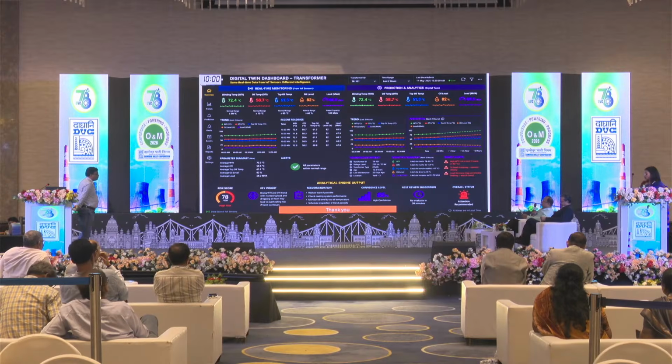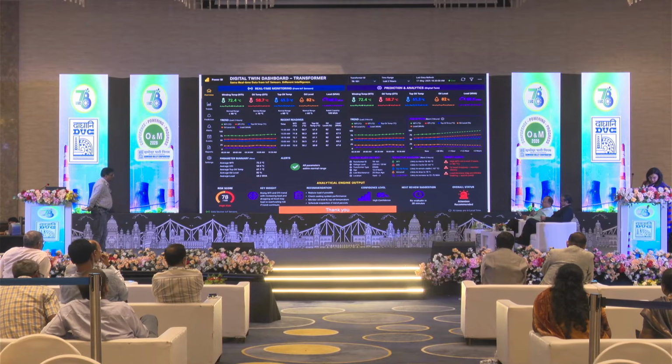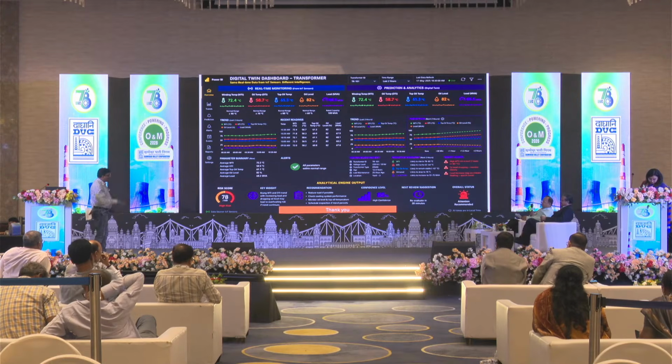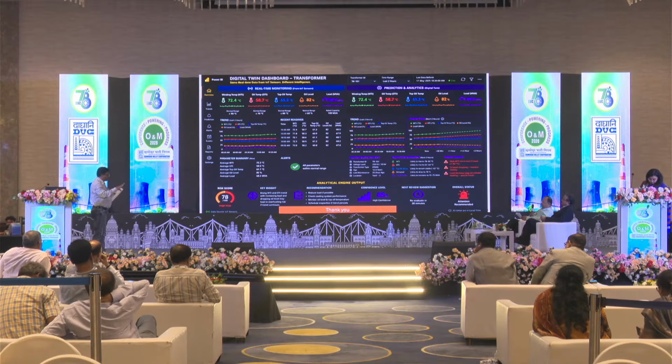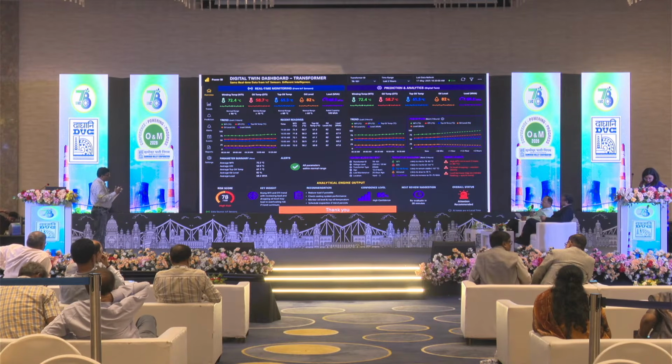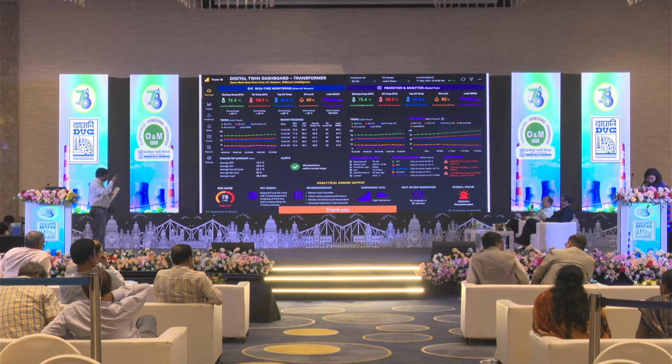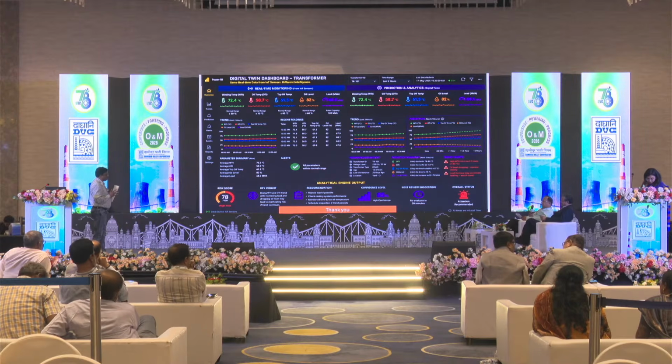Basically, to implement this digital twin, we require 24/7 online data for the transformer, like tan delta, DGA result. No, sir, my digital twin is limited to thermal only because it is a scalable model, right, sir? I have just made it for thermal property. For DGA or for any other, you have to scale it by converting all this through mathematical equations, or by incorporating an LSTM or gradient boosting model. I have not built the DGA in this, only the thermal property of the transformer.